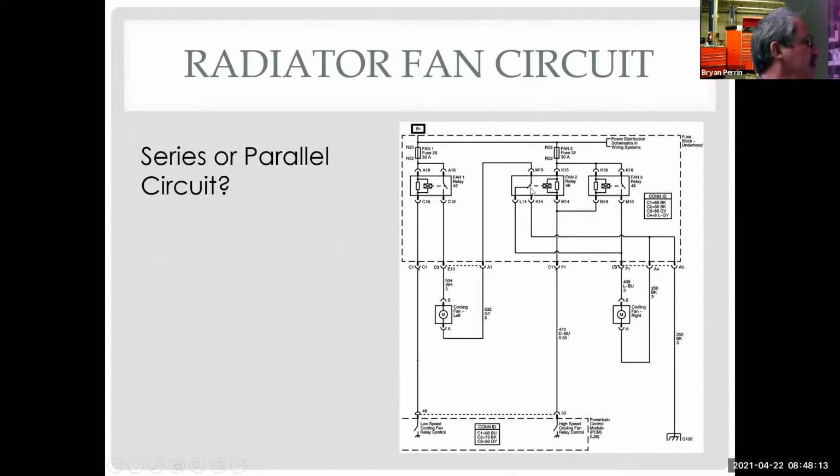Well, if I move this switch over, now I would come down power. I'm looking for ground, so we're going to go down this wire, and it goes straight to ground and doesn't power up the other fan motor. Which means that what? It's now getting a full 12 volts, not 6 volts, or it's not sharing its voltage. So that's my high speed. So the default position is low speed, and if I move this over, I get high speed.